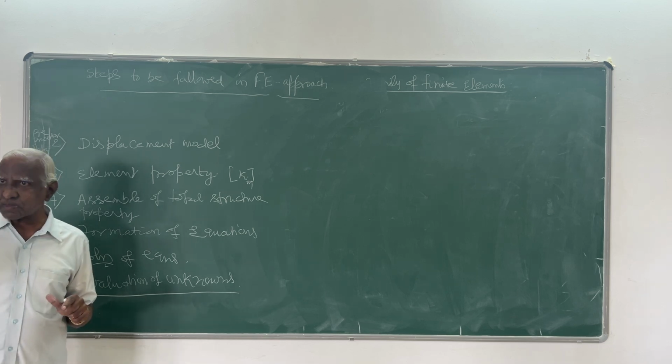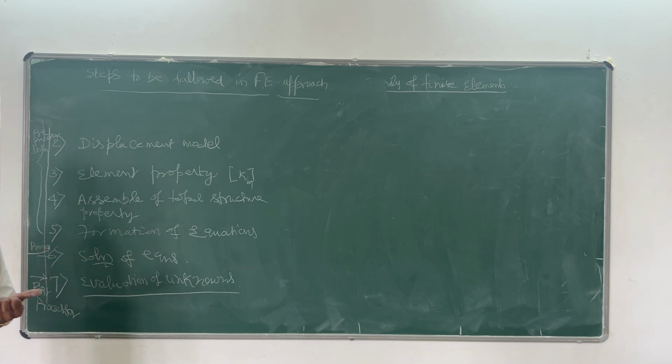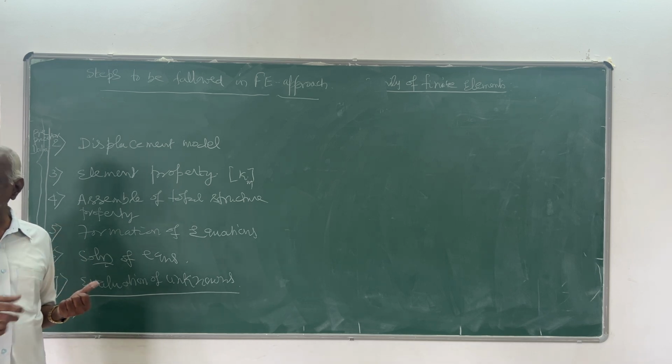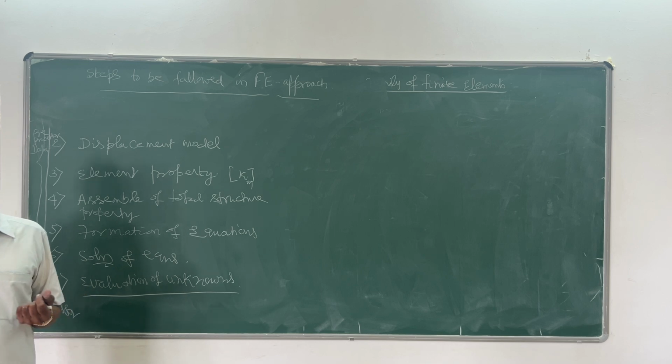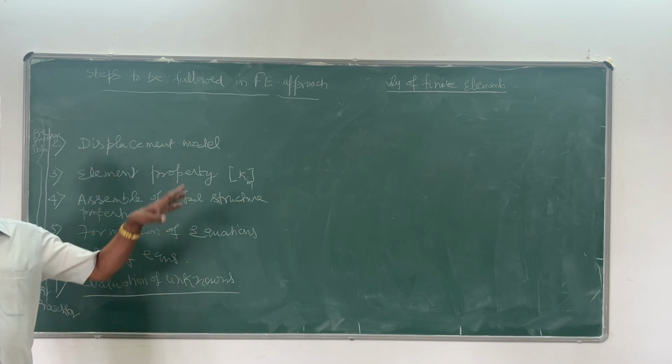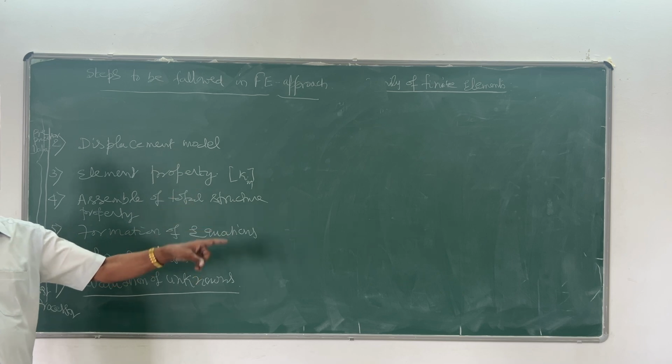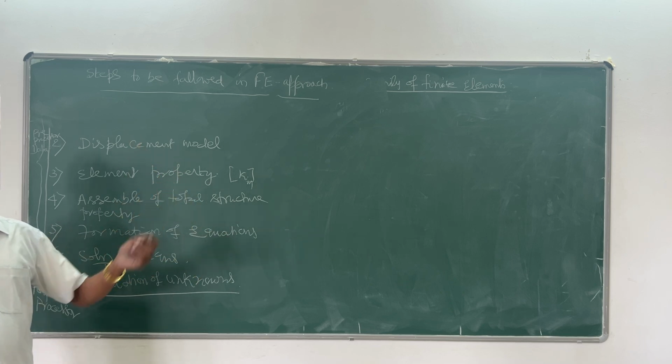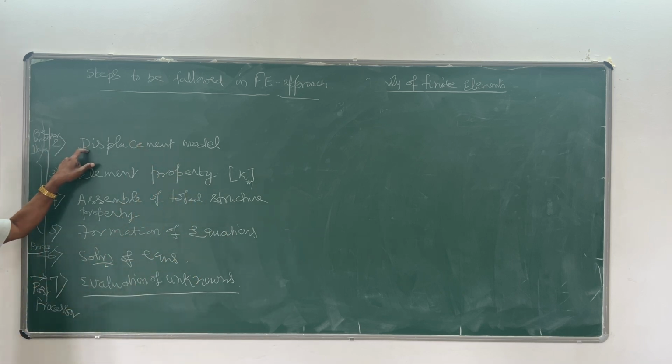In space frames, it will be 6, 3 translations and 3 rotations. So those are the classifications you have. You have analysis of planar structures only, so only beams, rigid plane frames, and plane trusses. At each node, how many displacements, I have told you.